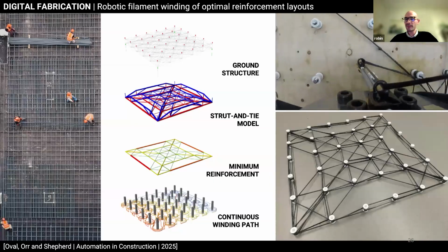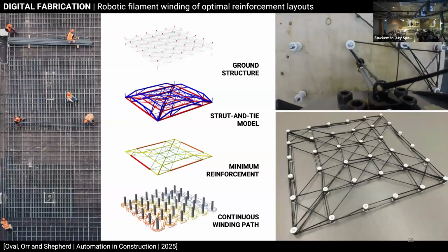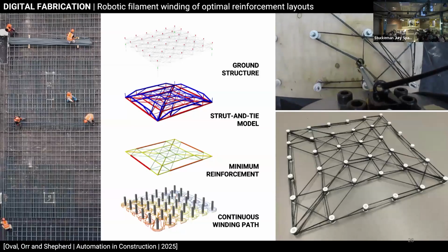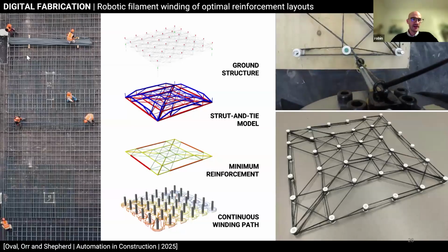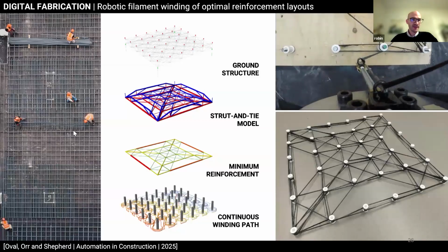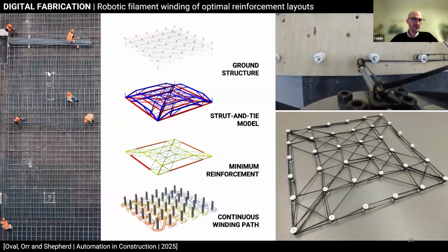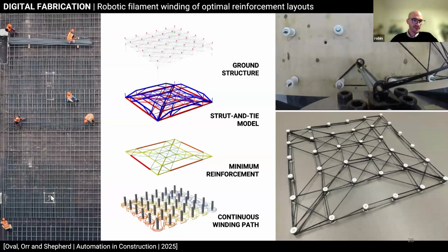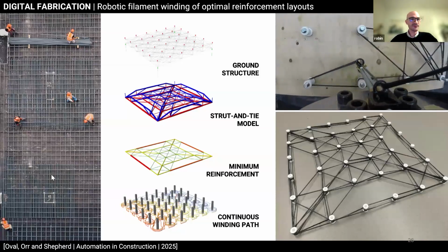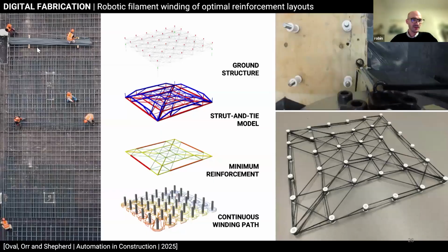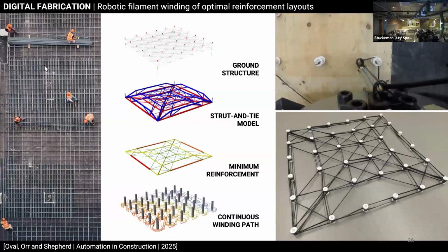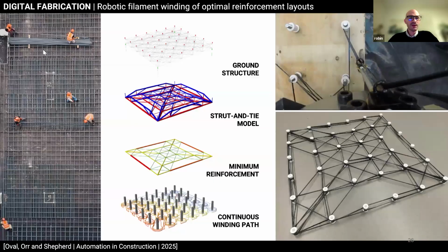It's not that much in terms of weight, but because the carbon density is way higher, and because of the way we build with these highly rationalized straight elements, so no complex topology there. If you want to reinforce around a wall like this or a column like this, you just stack, or you make it denser with a smaller spacing.